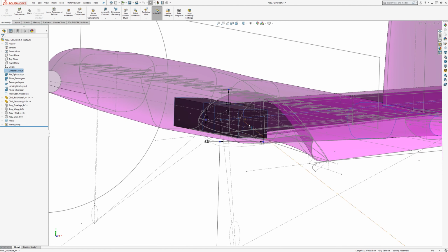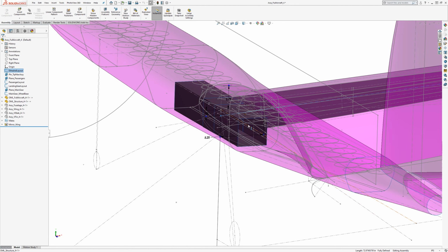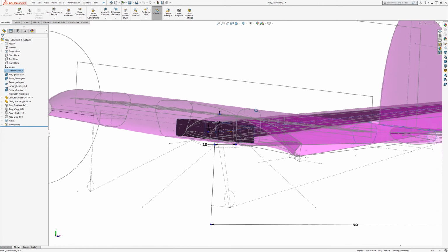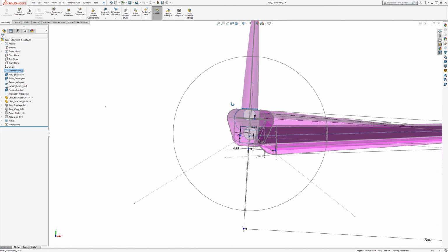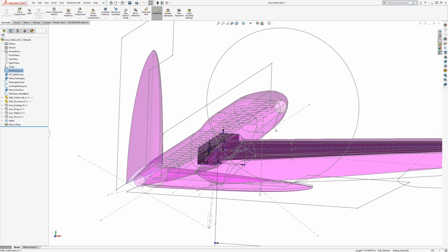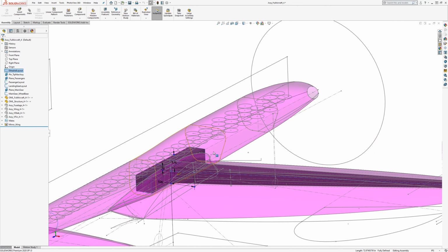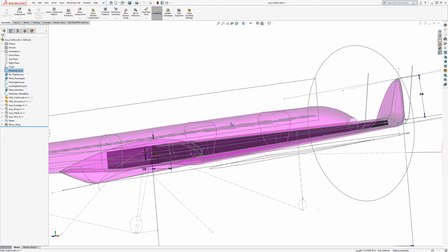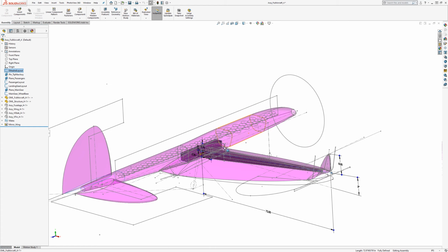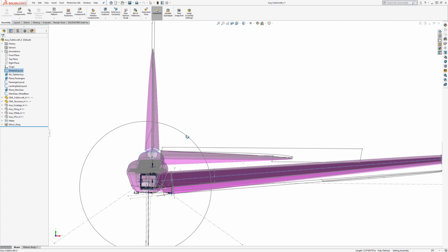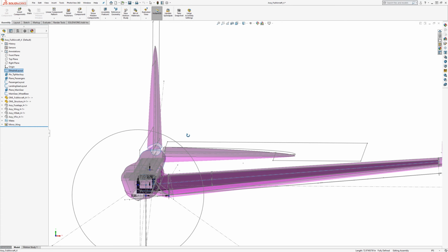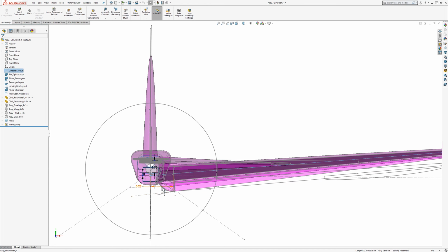But looking at it later on, I'm thinking that just the size required to make the fuselage, I don't think this surfacing in the end is going to be filled up in an efficient way by all the parts that need to be in there. I mean, the fuselage ended up being bigger than necessary, and the wing root fairing you can see is way low.